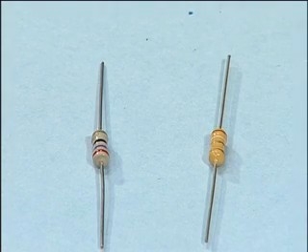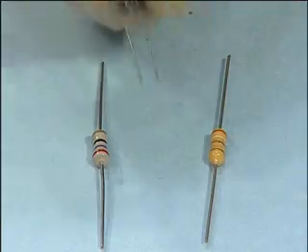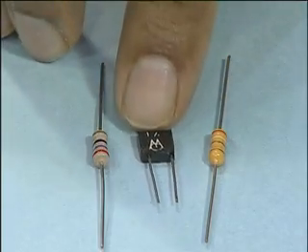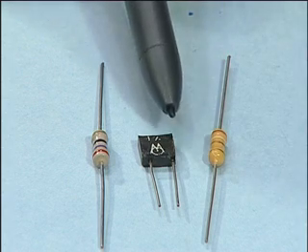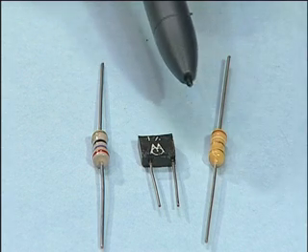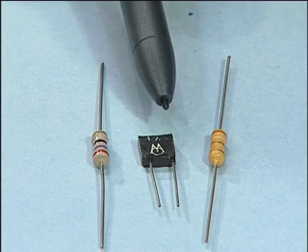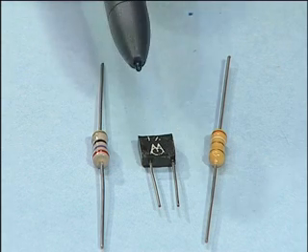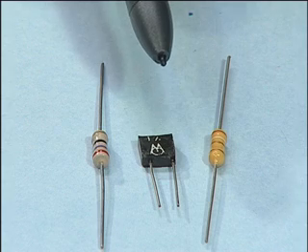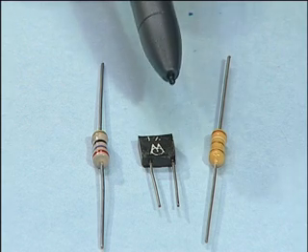I will put in a different type of resistor. You see this resistor here. This is a box type. This is made differently. This is called a metal film resistor. This is more precise than this in terms of variation with respect to temperature and such, and they are generally used for frequency tuning components.